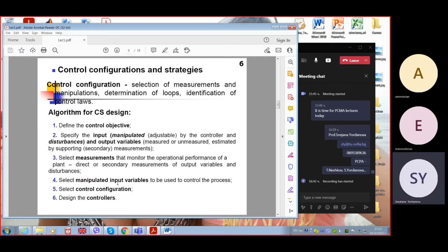And pressure or voltage or current is the output of a controller. So, the controller has two inputs. One is the reference, the desired value, and the other is the measured output. So we compare the measured output with the desired value we want for level, for temperature, and the error is processed under a given algorithm.